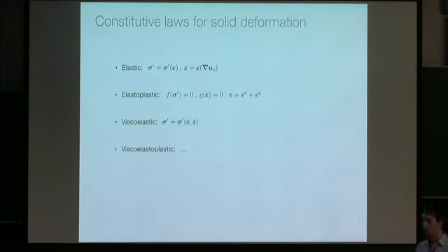So what this means is that the effective stress is a function of the strain, and the strain is then a function of the deformation, meaning the gradients of the displacement field. And the reason that this is a headache compared to, say, a viscous rheology is because then you need a reference configuration, and you always need to know how far you are from your reference configuration. And that calculation and the geometry associated with that becomes a bit of a mess when the deformations are large.